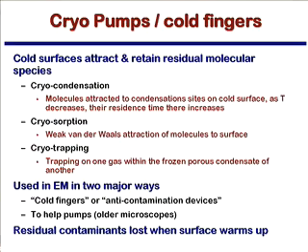Usually what will happen is you'll hit a button and it'll say, okay, I'm going to shut the ion pumps off, turn the turbo pumps on, and then heat this thing up so that all the residual things now go out the turbo, right? And you do that for a couple of hours, and then the system turns itself back to the state of having the ion pump in. So it's all organized for you when you hit a button on the modern system, okay?